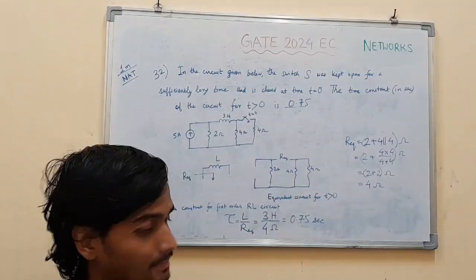I've shown the detailed steps. First, applying basic circuit analysis, KVL in the left loop to obtain I1 in terms of V1 and V2: V1 minus 2 I1 minus V2 equal to 0. Next, writing KVL in the right loop, we obtain the relation between V2, I1, I2 and V1.